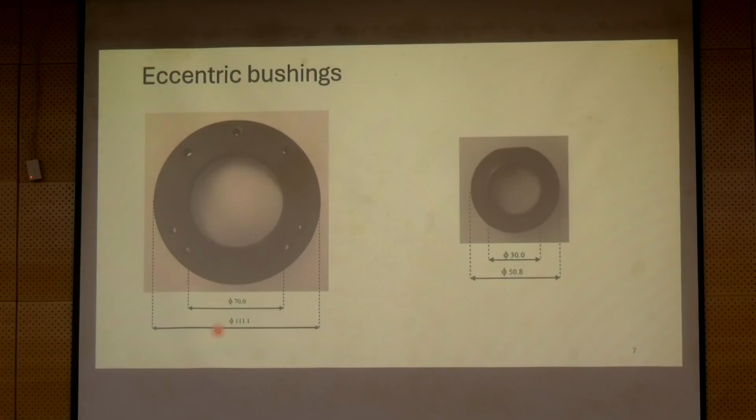Okay, the dimensions will be based on the bearing you want to use. So if you know what bearing the motor is supposed to have, then based on that you can decide the dimensions, and the air gap, or the eccentricity severity, will determine the offset. The bushing on the right side is a bushing that will help us achieve a wobbling motion of the shaft.